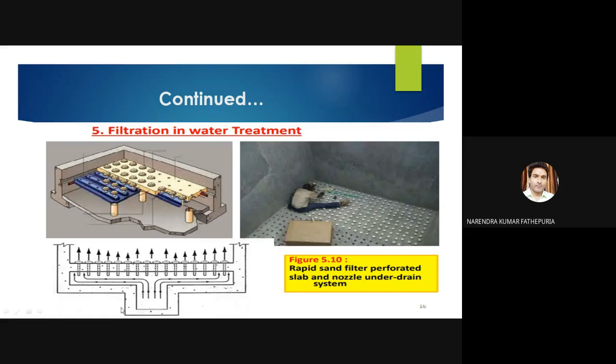For backwashing, water has to be sprayed from the bottom onto the bed, because the main function of backwashing is to clean the filter beds, to open the pores and voids available in them. So all the impurities will wash away with the drainage system, and the filter bed is ready for further treatment for the fresh discharge.